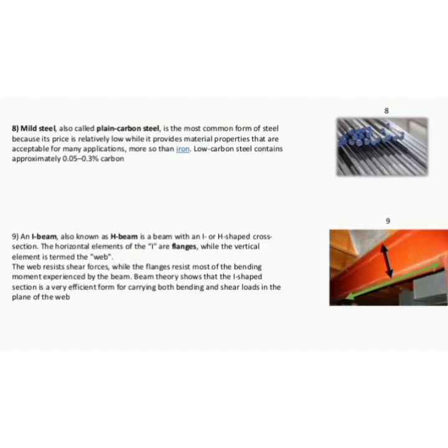Mild steel, also called plain carbon steel, is the most common form of steel because its price is relatively low, while it provides material properties that are acceptable for many applications, more so than iron. Low carbon steel contains approximately 0.05 to 0.3% carbon.